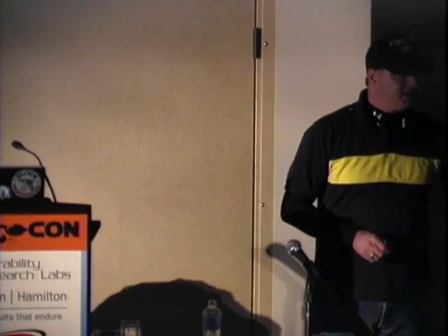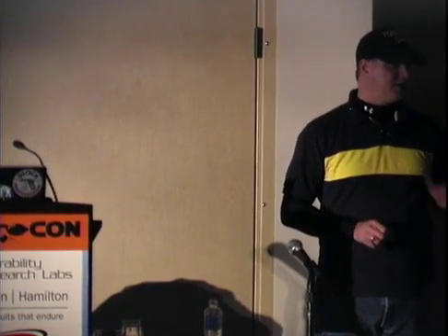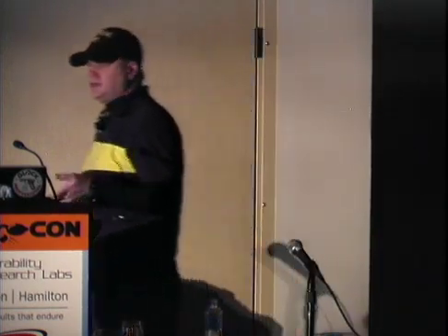The other thing is, SMART tables can actually cause the drive to fail. In other words, you don't need SMART. It provides you nothing that you need to make the drive work, but it can stop your drive from working. The reason I say this is that the drive loads the system area, it loads the content from these tables, and if the tables are corrupt, there's very little error checking to say, hey, I didn't mean for this buffer overflow or something else to happen. It causes an exception failure, and the drive's code sees an exception and just falls over. It doesn't do anything else at all. It just stops and basically freezes in time with a firmware failure because of the SMART table.